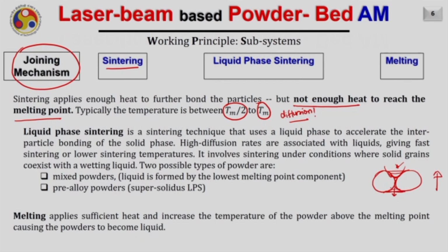So, this is a typical mechanism for solid state sintering. The foremost advantage of solid state sintering is its adaptability with any material. A wide range of materials can be processed with sintering, from polymers to metals, and even metals and ceramics coated with some polymers.